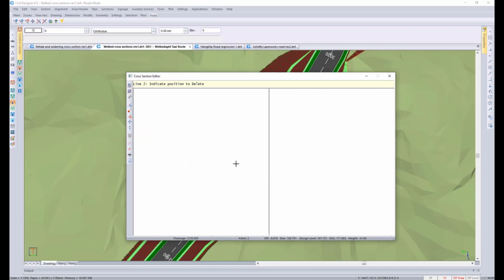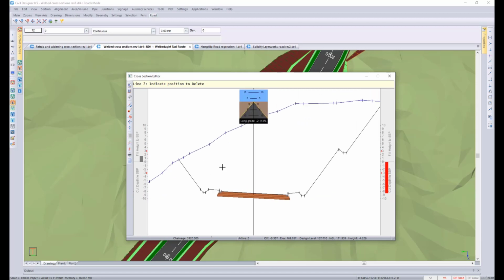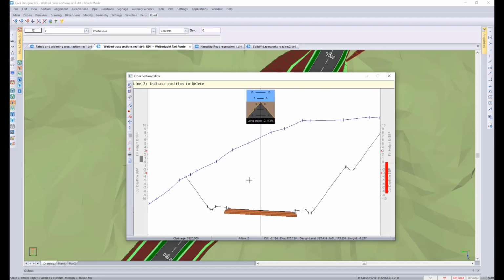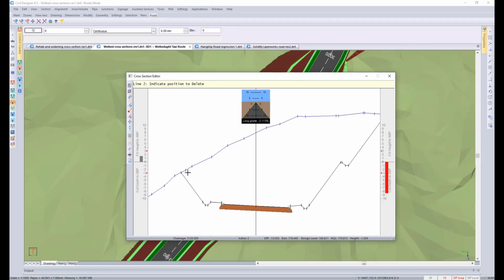So that line intersection would be necessary over there. Another reason for line intersection would be if you're doing a polygon area and you don't have a point. So you could do that polygon area over here, and you click on all your points on the cross section to calculate an area. And then you would need a point there at the change of direction as well.